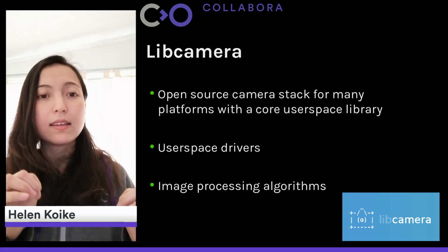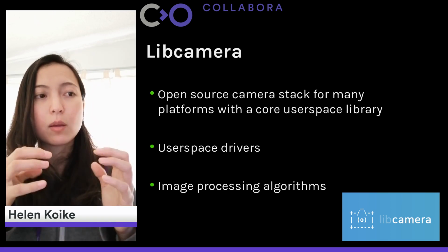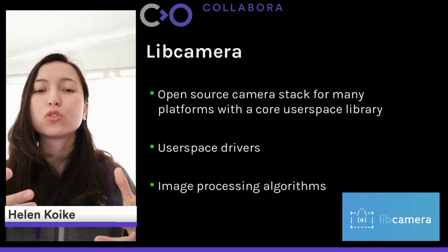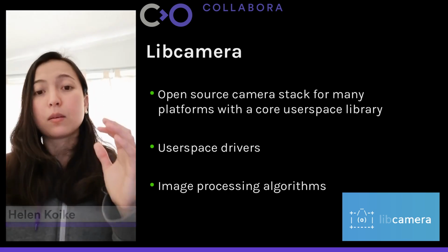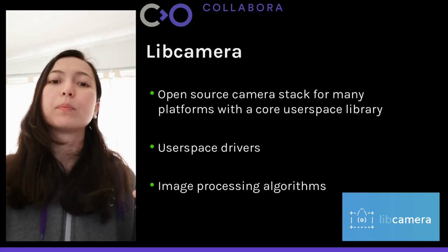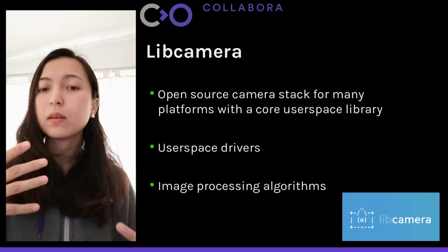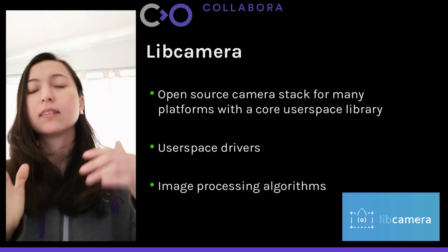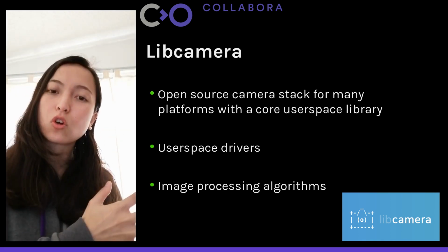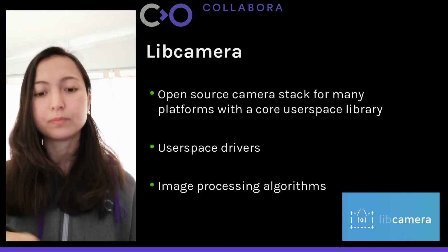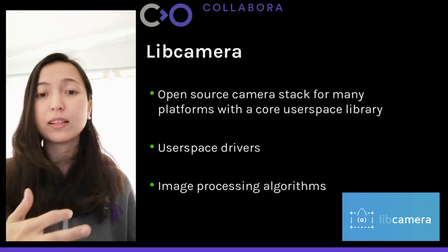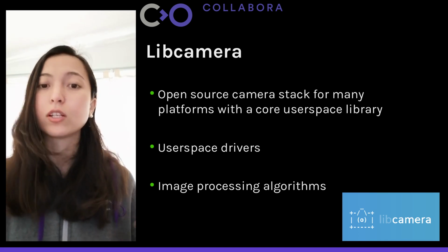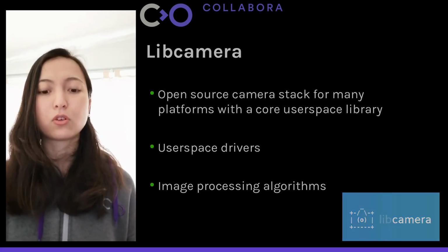What is nice is that libcamera allows you to plug in your own image processing algorithms as a plugin, so you can plug in your proprietary algorithm, and it separates the open source part from the proprietary part really nicely. We can think of libcamera as the equivalent of the Mesa project for the graphics world, but for the camera world.